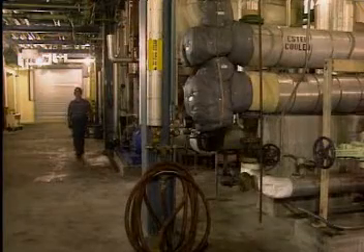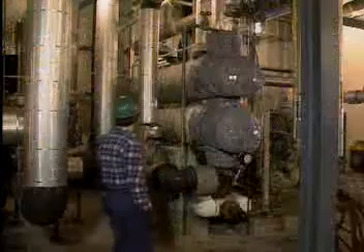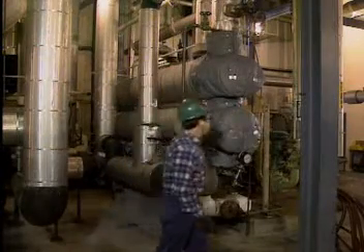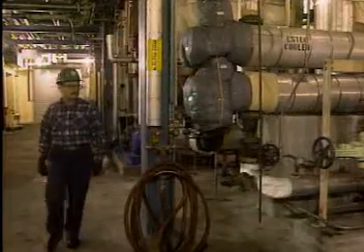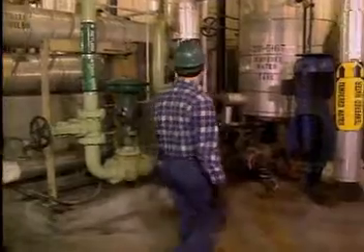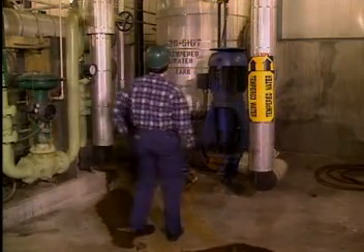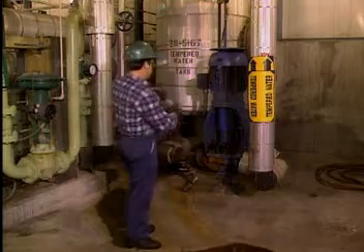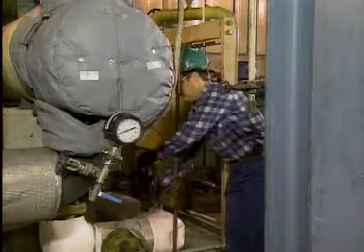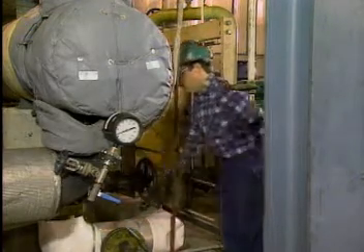Before starting up the heat exchanger, the operator inspects the unit to see if it's ready. He checks the valves to make sure that all of the isolation, vent, and drain valves are shut. After he completes the initial inspection, he establishes the cooling water supply to the unit. He does this by calling the control room operator and having him open the shell side vent. Then he partially opens the shell side water inlet valve to slowly fill the shell side.